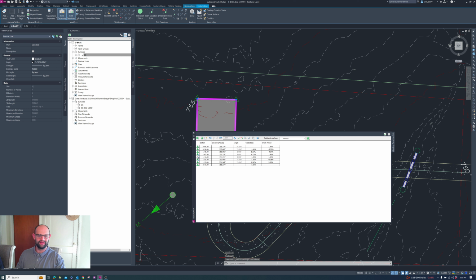We have another grayed out vertex here. PI, we'll fix that later. Right now, I'm going to click any one of these elevations, hit Control A to select all of them. I'm going to click in one cell and type 753, that's the desired elevation, and it's going to move all of those PIs to that elevation.